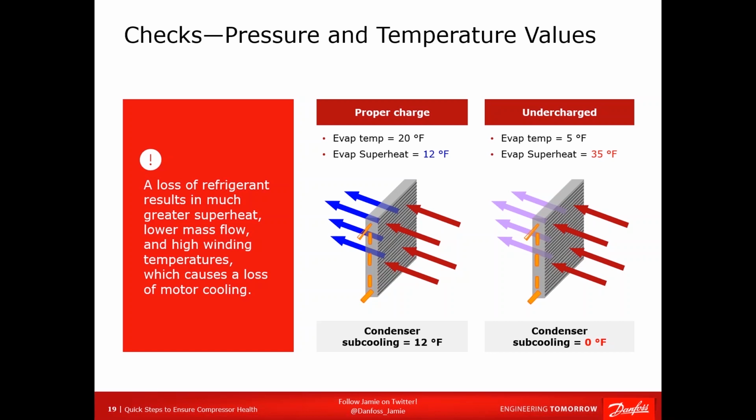Well, here's the thing. Where'd the refrigerant go, right? Did somebody undercharge the system to start with? Yeah, that usually doesn't happen too much. If anything, they're almost always overcharged. I would really be hesitant to charge it without first finding out if it leaked or not. Because again, you can add refrigerant charge, but you're only going to be coming back again if there's a leak and doing this over and over again.